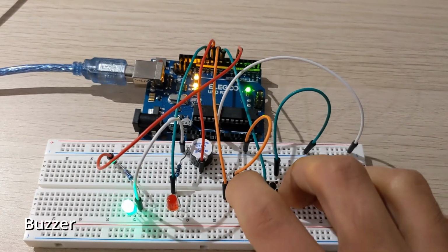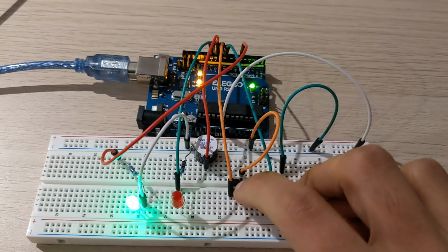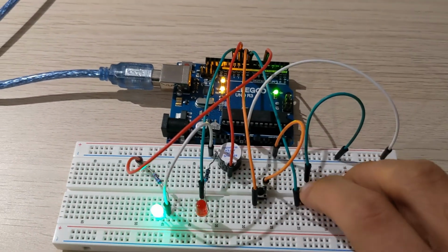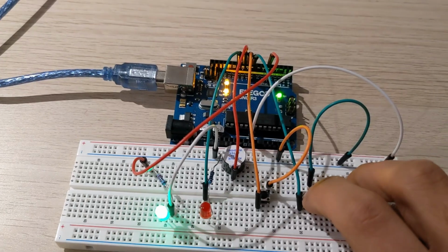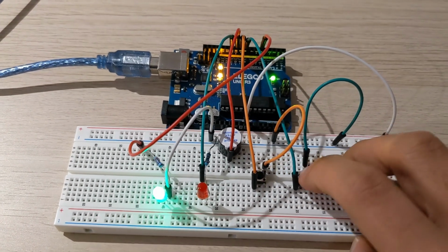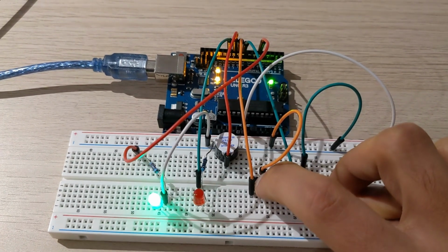From the guide it says, we should be careful not to use the UNO R3 board analog write function to generate a pulse to the active buzzer, because the pulse output of analog write is fixed to 500 Hz. I've just happened to use analog write, and this is the result of varying the pitch of the buzzer.